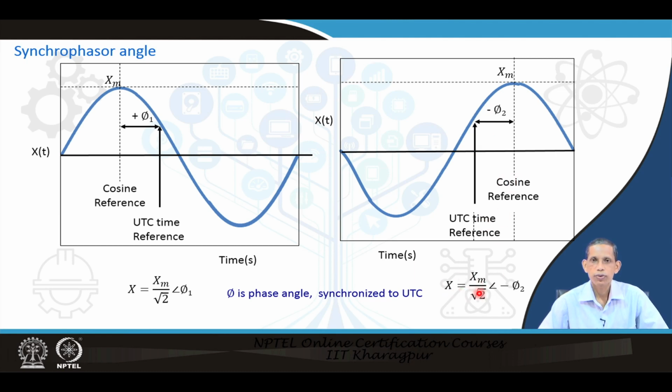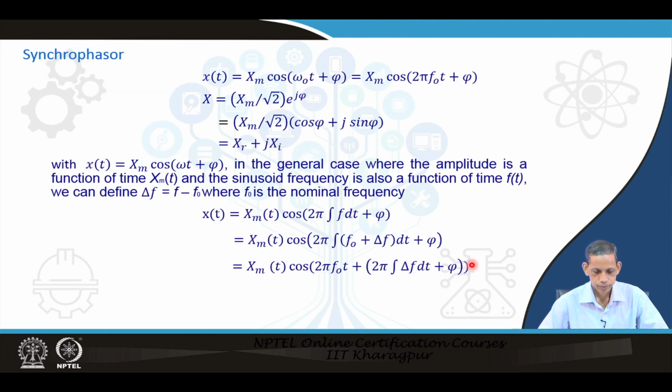In that case, the corresponding phasor is assigned a negative angle. This approach is used throughout the applications of the PMU concept, and it is a standard practice in this domain. The synchrophasor computes the phasor. Note, this kind of phasor estimation we have discussed in relay. Even though it is similar, the accuracy level demanded for such an application is very high.